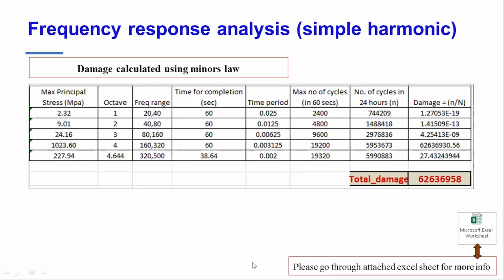So what goes in here? Here again, your Basquin's equation goes in. Here again, your Miner's rule goes in. What is changing here? The only thing that is changing is getting an idea of how many cycles you have to expose your stress to. If your sweep time is fast or slow, the number of cycles to which you have to expose your maximum harmonic stress will vary.